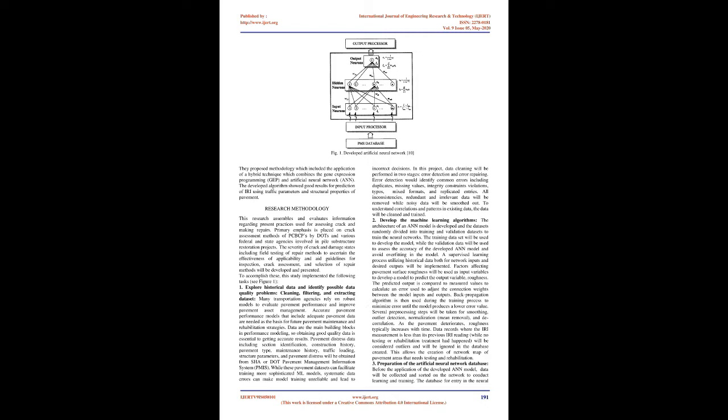3 individual ANN models for prediction of 3 key indices, crack rating, ride rating, and rut rating used by Florida Department of Transportation for pavement evaluation purposes were developed. Results of the combination of the individual models suggest that the developed ANN models have the capability to satisfactorily forecast the overall pavement condition index up to a future period of 5 years. Roughness level probability prediction using multiple linear regression and ANN was studied. Obtained results indicate that ANNs have a superior ability to predict the probability of roughness distress level compared with multiple regression methods.